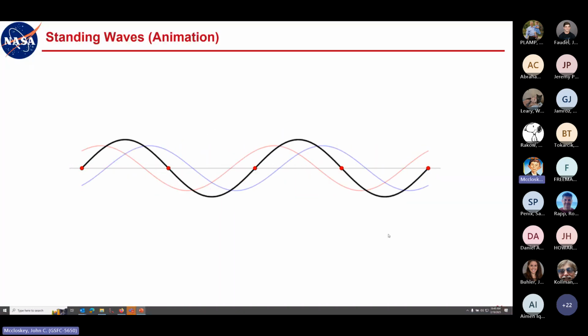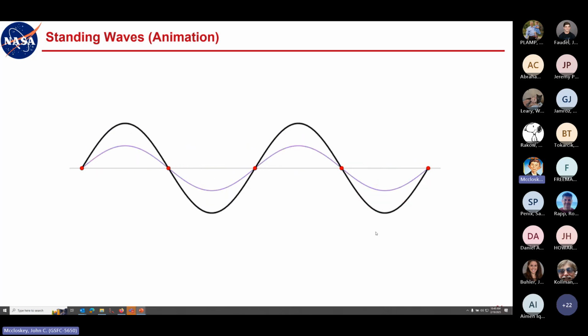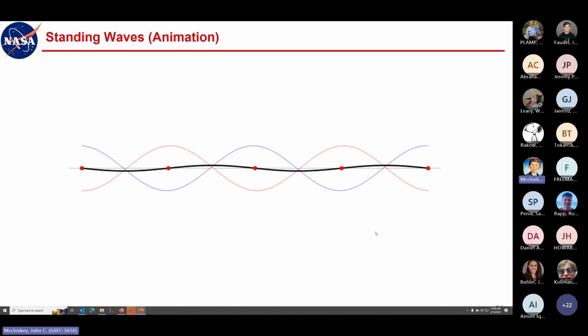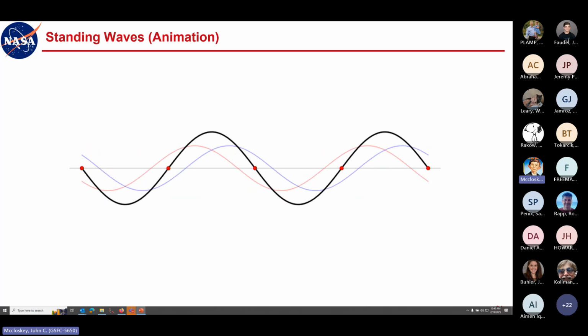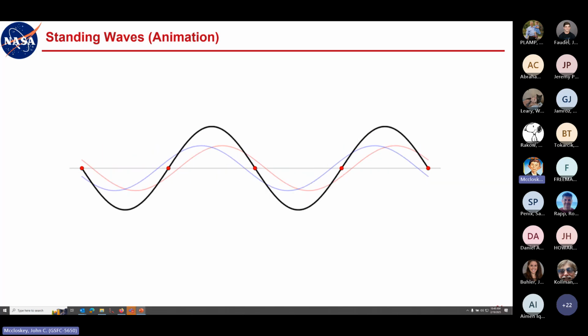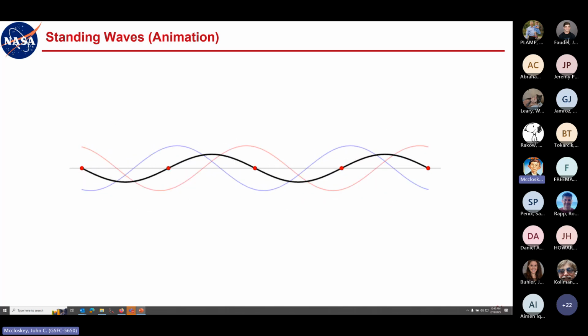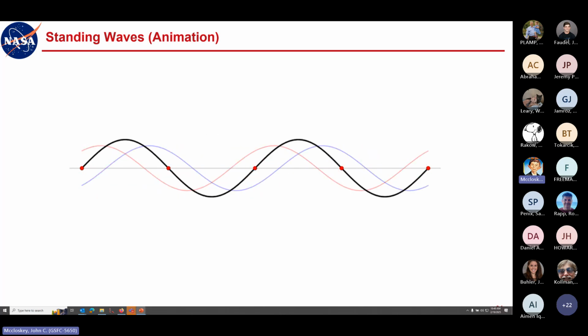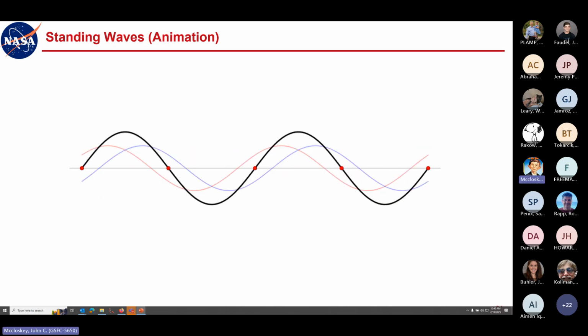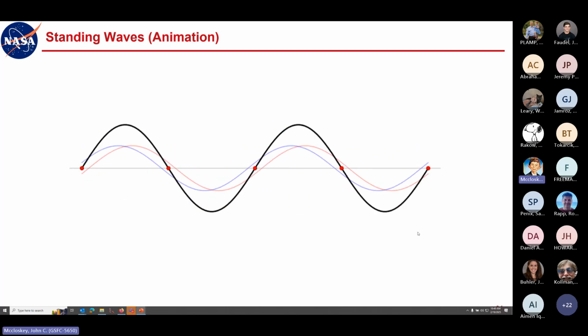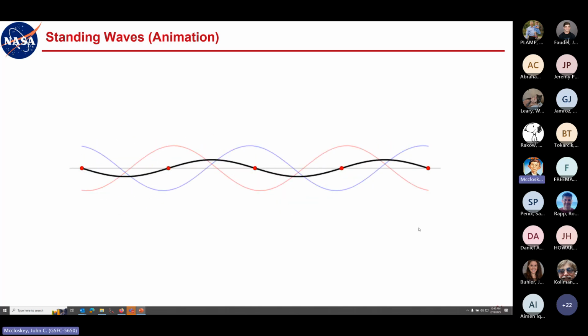So this is the sort of thing that you will observe when you're trying to make common mode measurements on this type of configuration, where you've got what is essentially a transmission line with a 300 ohm characteristic impedance terminated in a short at both ends. So this is just something to pay attention to when you're making these measurements at higher frequencies.